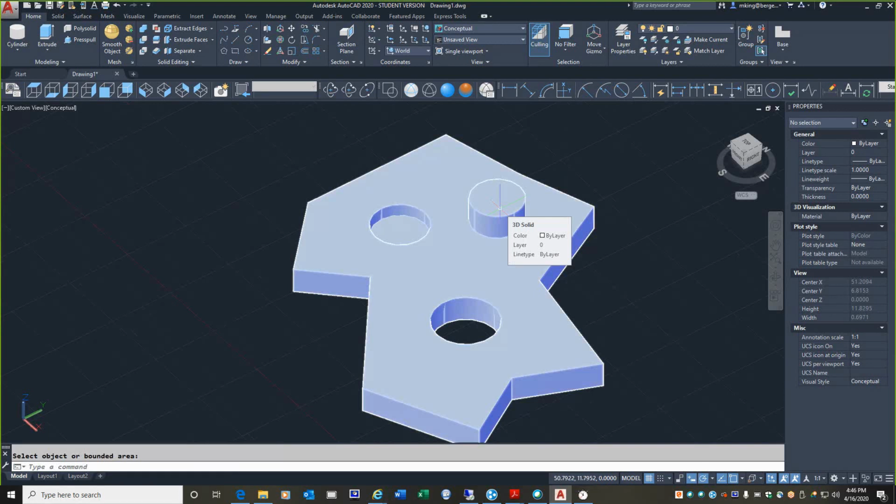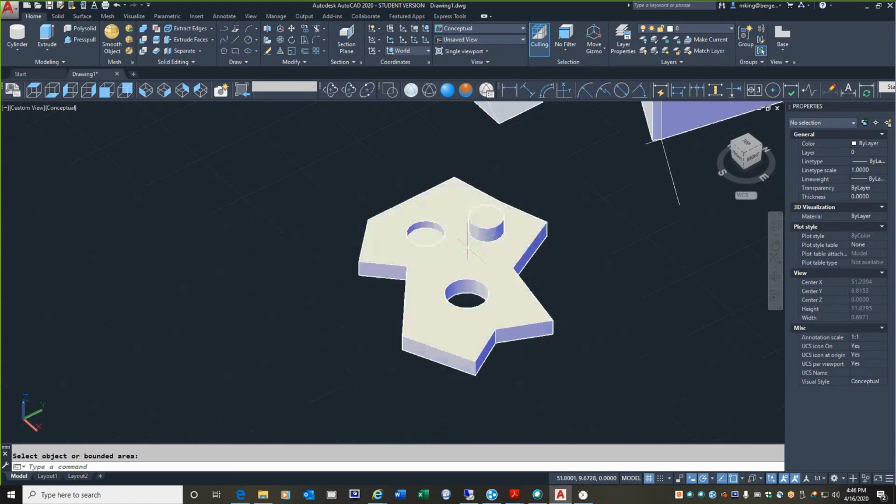Okay, so press pull gives us a lot of opportunity to create some elaborate shapes. Okay? And realize we're doing this by drawing in 2D and then creating a 3D shape from our 2D geometry. So again, the value of mastering AutoCAD with 2D comes into play here.